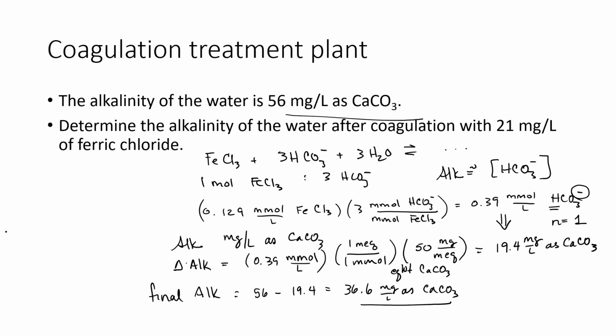Professor, can I ask how you got the 50 milligrams per milliequivalent? Good question. Is that just given? Yeah. Okay, so if I calculate the molecular weight of calcium carbonate, that is 100 milligrams per millimole.